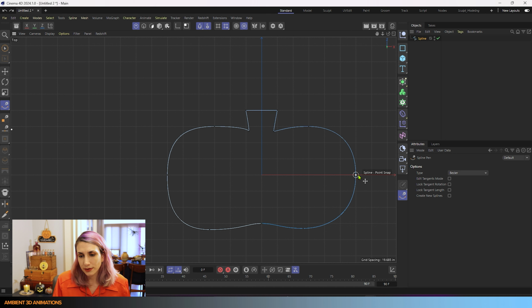You also have other options here. So if I were to right click on this portion of the spline, you can see we have options to delete this edge. We have options to add a point. So like what we did with Control or Command on Mac, Control on PC, you can add a point here doing that, or you can click this button here and it'll add in a point. You can also